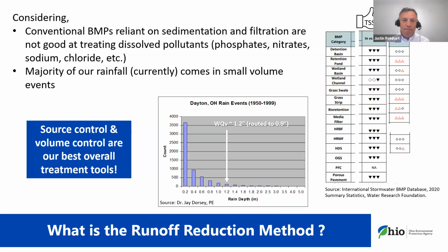for stormwater management. Okay, so why is all that important, or what's the significance of that thought process? What's good about it? Well, on the stormwater water quality side of things, consider two things. First of all, that added volume reduction brings with it the benefit of a reduced pollutant load. While our primary BMPs are reliant on longer gravitational settling and retention times to capture suspended solids, and they work really well to do that, they're generally fairly ineffective at capturing dissolved pollutants.